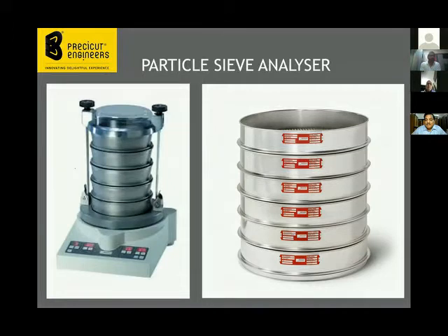Now first here is basically the particle sieve analyzer. This is just a multi-deck vibro sieve. Each deck will have one wire size of wire mesh. Each size will represent a respective size as per the SI standards, and this size will be applicable to that particular shot size.